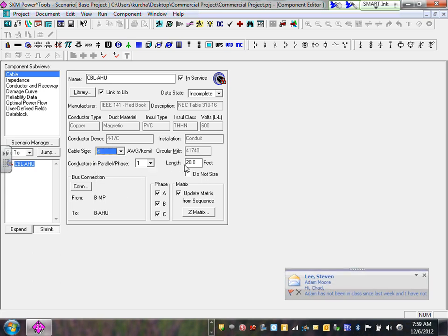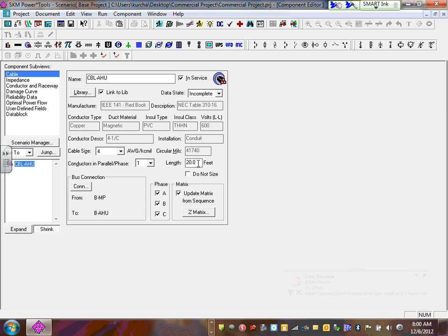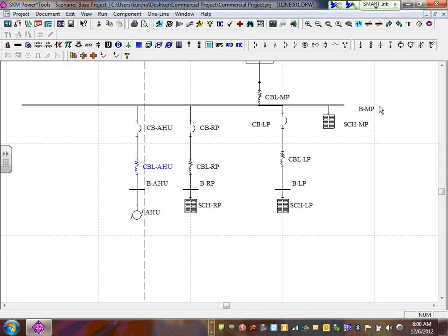And we're still using how many feet? Now remember, the air handling unit was inside the room. So we're using EMT conduit, the same EMT. So 20 feet, let's give it 30 feet because it's slightly more. Put 30 feet for that one and exit, because it's right next to the panel. Okay, so what I did, guys, I used number 4 conductor in this cable and 15 horsepower for this air handling unit. Any comments, any questions?